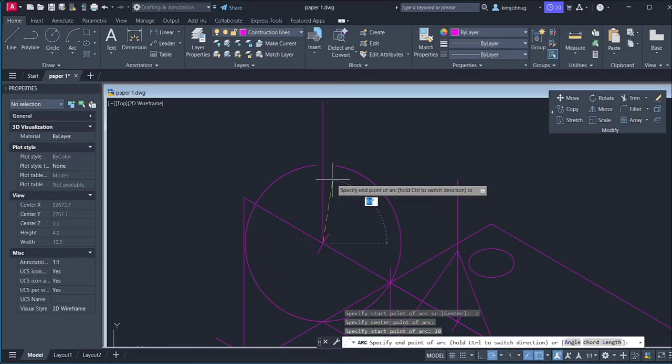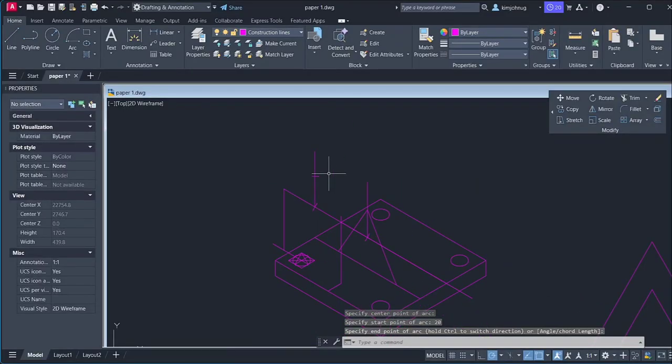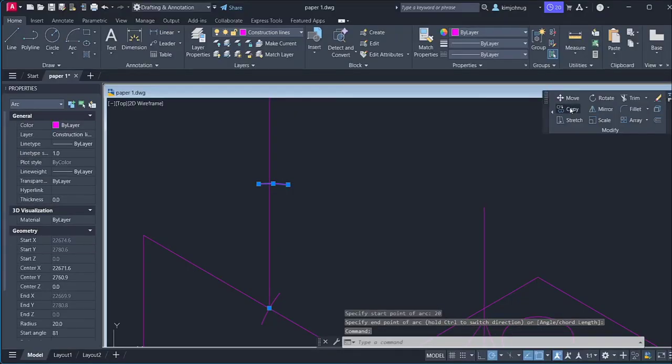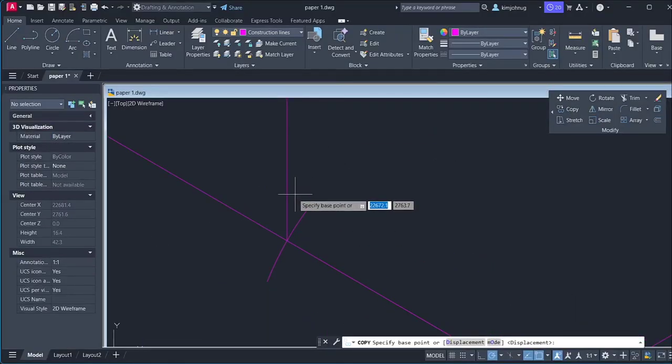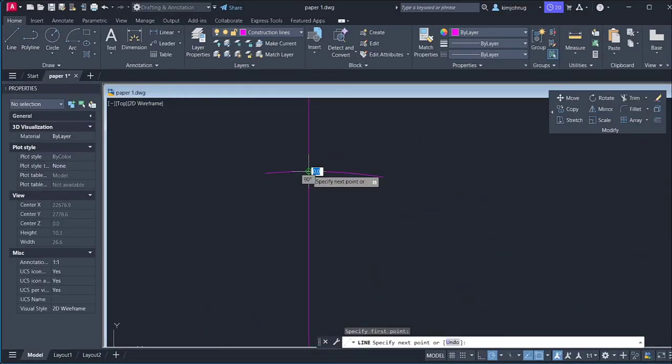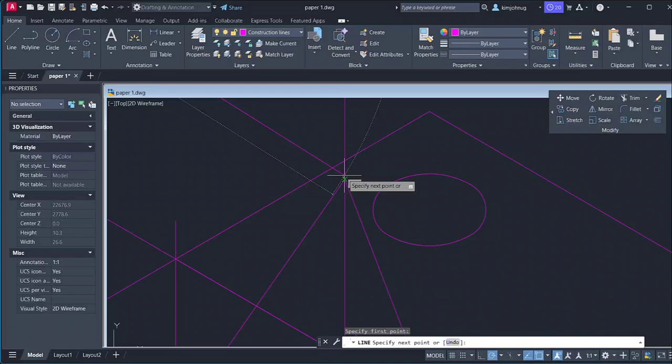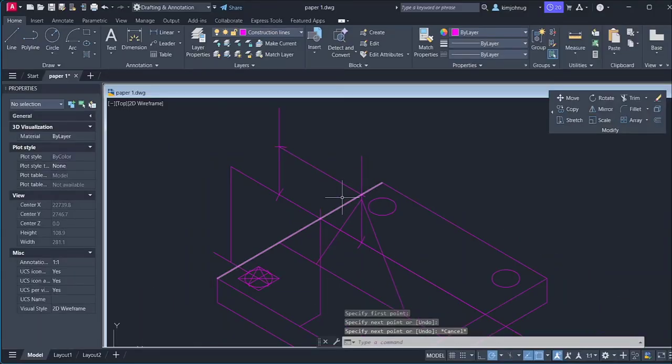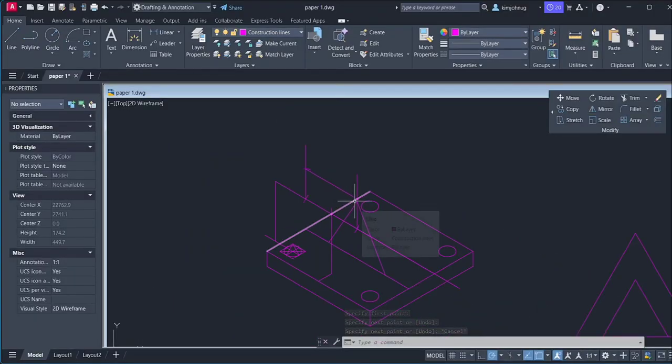With the trick we learned, you press Ctrl and then you draw. I want to copy this arc anyway, and I just do a line. Color tracking is there, right? If I do a line from here to guide me, whenever you see that green, green is the guide. So that's where I connect. That's inline. I have a semicircle here of radius 20.